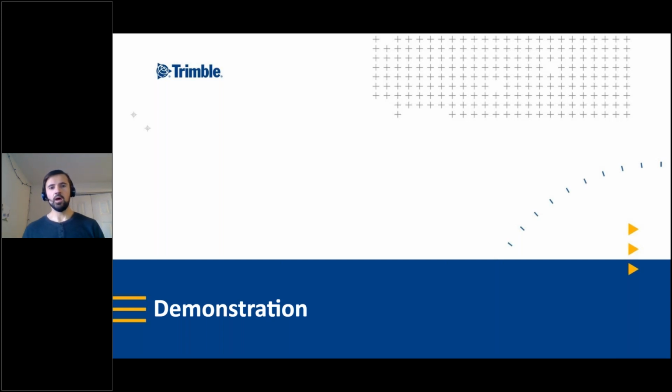So yeah, how the monitoring module in TBC works is it's all based on point ID. So every time I measure that point in the field, let's say I'm measuring the face of a building, and I call that point 100. Each time I measure that point, it's point 100, and that's how we designate how we compare the data over time.